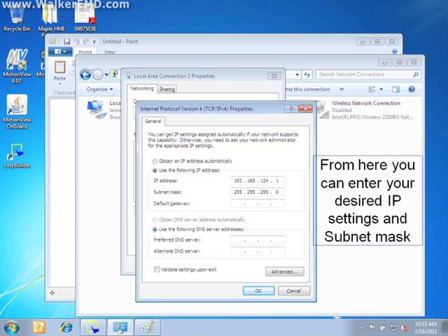The default value of the position servo's last octet of its IP address is 120, so any address other than 120 will work if the only two devices on the network are the PC and the drive. For example, you could set it to 1. Enter 255.255.255.0 for the subnet mask, and then click OK.